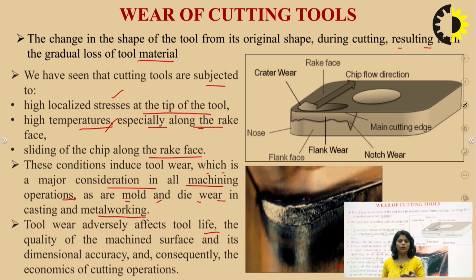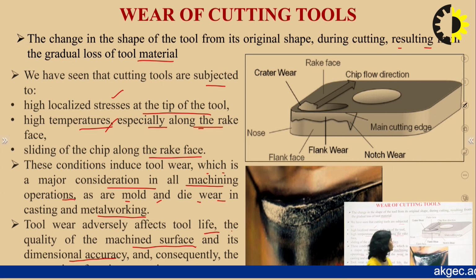Cutting forces will increase, and the quality of surface finish will also change. Okay, we will get poor surface finish here. So tool wear adversely affects the tool life, the quality of the machined surface and its dimensional accuracy also, and consequently the economics of the cutting operation. So tool wear is not favorable. We have to look at the factors through which we can reduce the tool wear, and the corrective actions we have to take.